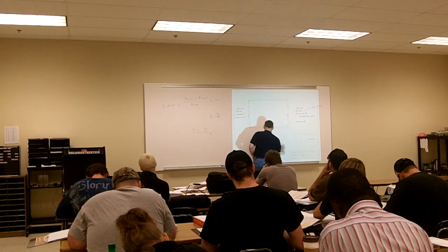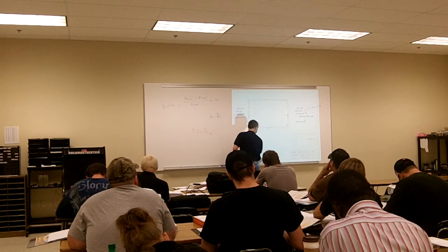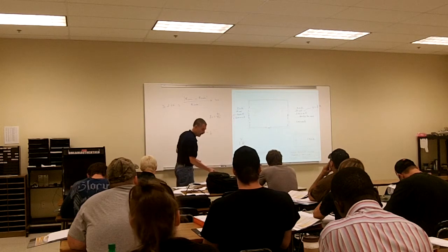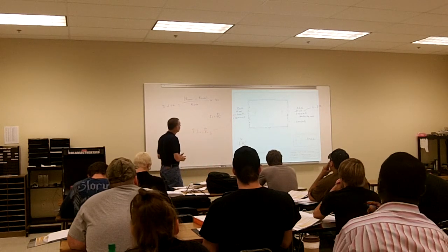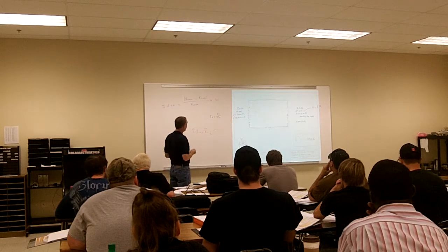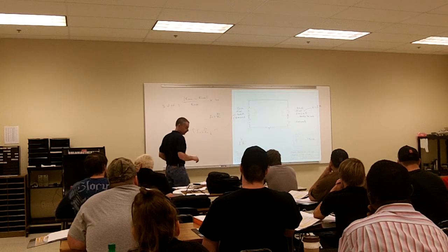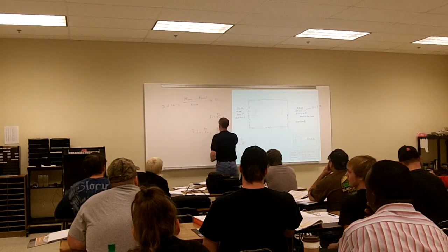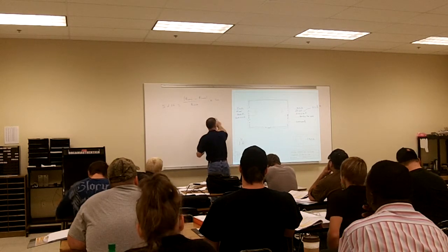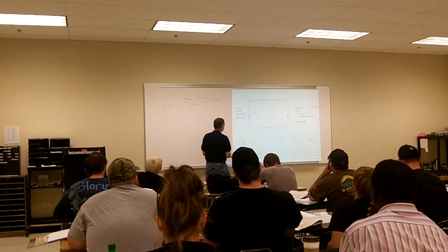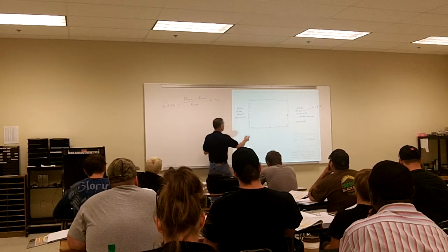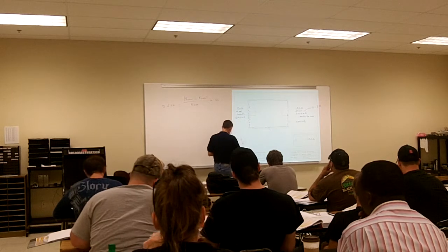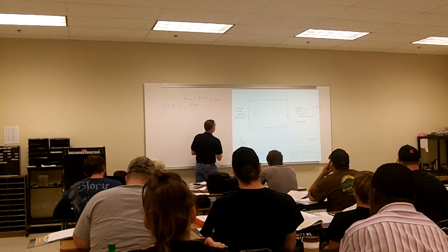Where would be a good place for me to start? What would I want to do? What would I want to make sure that I definitely have? Power sources on? Yeah, make sure your power source is on. First thing I want to do is just double check and make sure my power source is on. So what I'm going to do is I'm just going to put my voltmeter across there. And we're going to say that, yep, we got that.